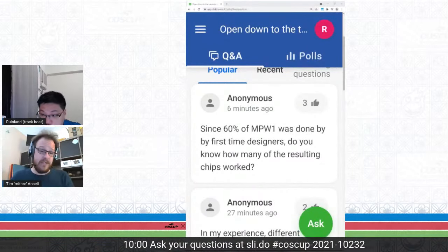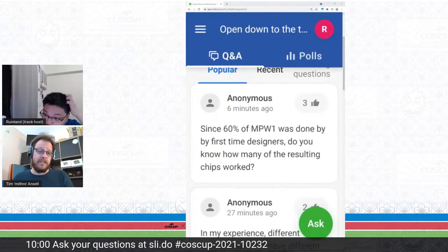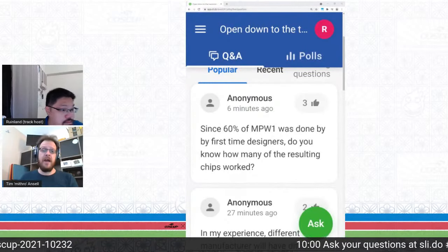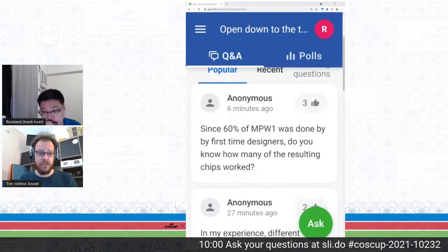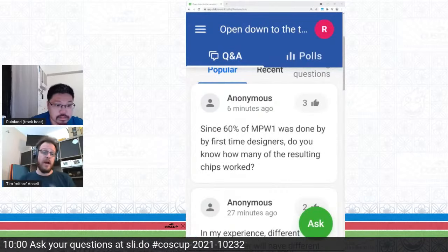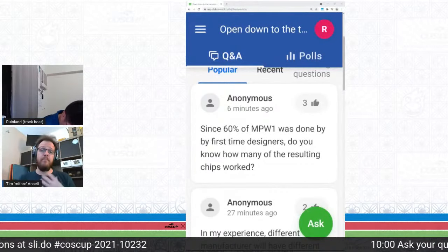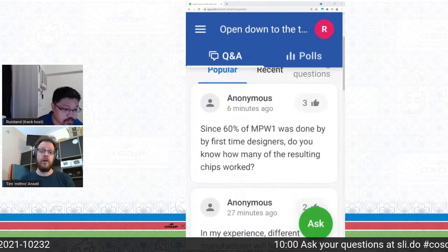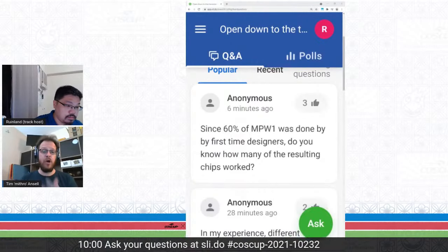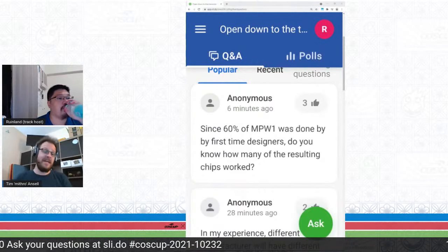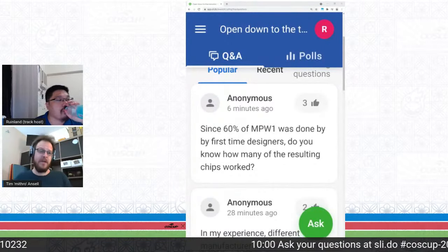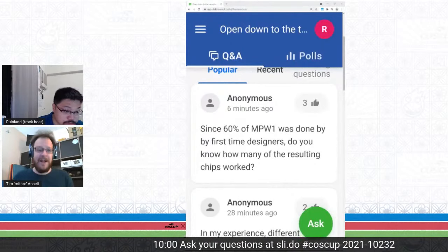The interesting thing is that all results were DRC clean, because the OpenRoad tools are only supposed to produce DRC clean results. This lowers the barrier to entry quite a lot. As well, by having that harness, we can build things like the ability to turn on and off the I/O without the rest of the system necessarily working. And there's this idea that if you turn on a part of the chip and the chip stops working and starts smoking, maybe you shouldn't turn on that part of the chip again.